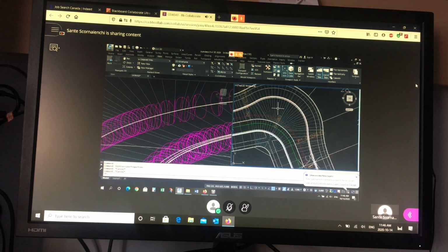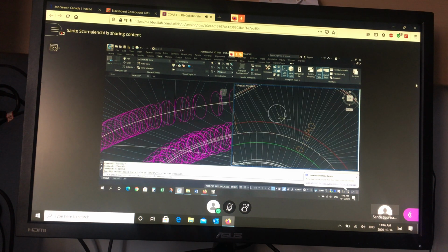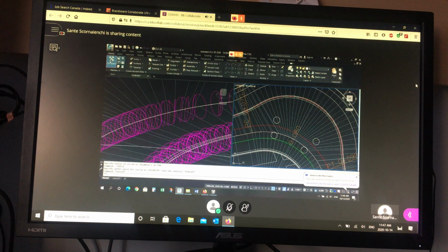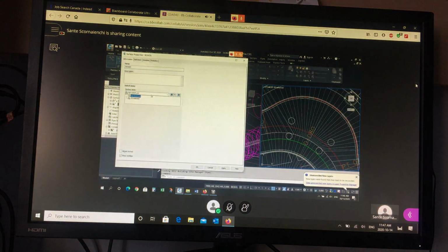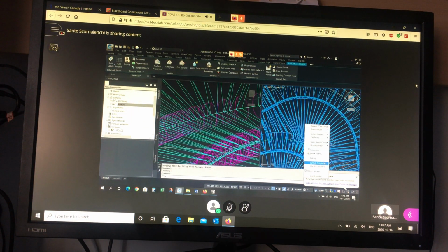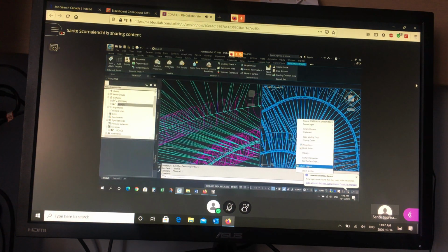Why is this pavement important? Well, when you put in maintenance holes, now it knows what the elevation of the top of the maintenance hole is. From the surface, remember there's a surface here. Let me bring back the surface. The surface roads. When I create my database, it'll get the elevation for the top of the maintenance hole from this surface. So and let's look at this in 3D, object viewer.